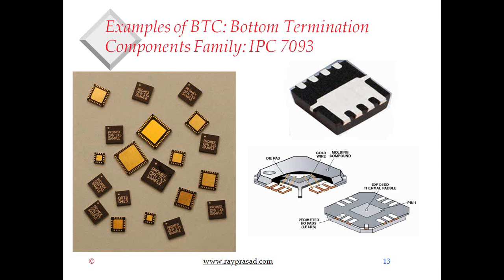That's where they started, and it will become more clear later on. And this understanding is very important. So you have a sheet of copper that's etched out, and then that makes the lead and thermal pad. They are now not connected to each other, but this was all one piece of sheet of copper. And then the wire bond is what's connecting all these leads to the silicon. And then once you're done with that, you just mold it, and there you are. You are done with this package.